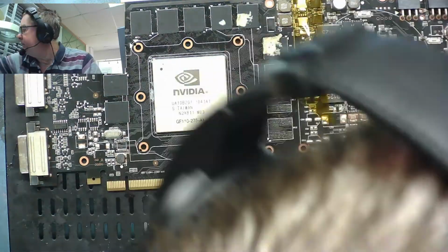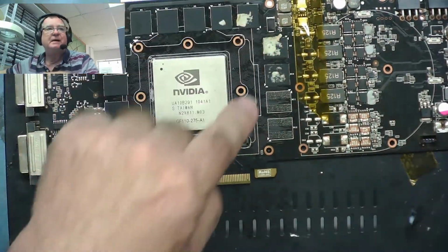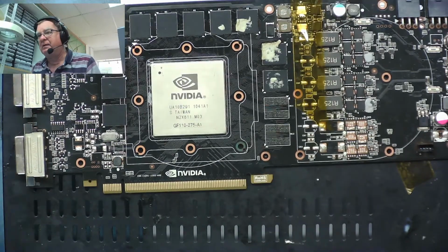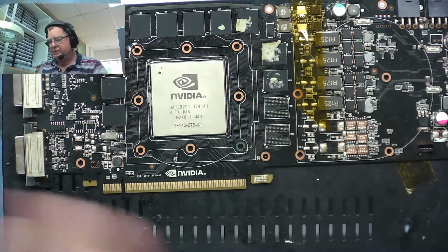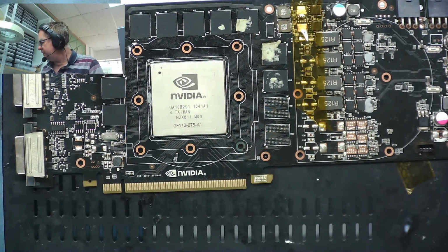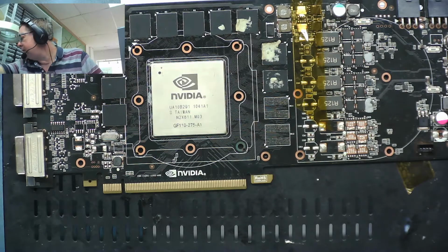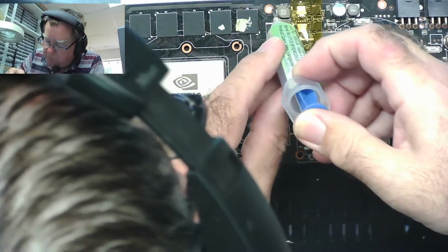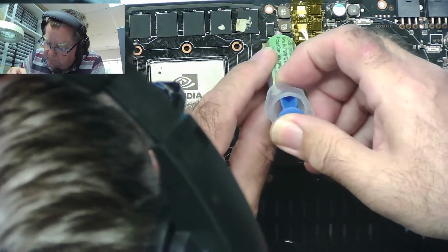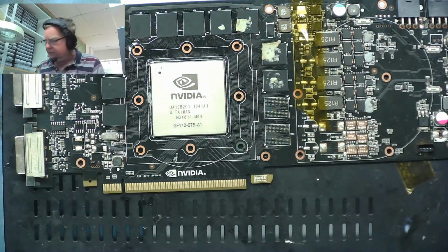I'm going to get the soldering iron and try to get some leaded solder on either end of these as well now. I've got some warmth into it. Just one moment while the soldering iron gets hot. It'll take a few seconds. Let's get a bit of flux on them. This will help them to unsolder if we put some leaded solder at the end of them.